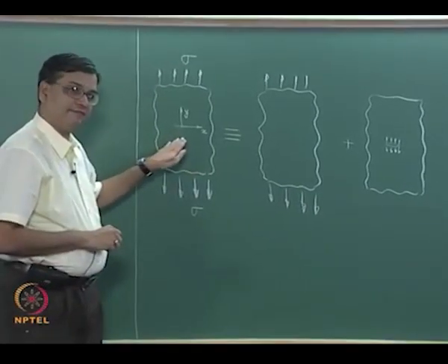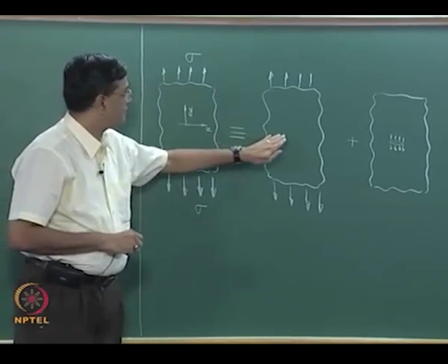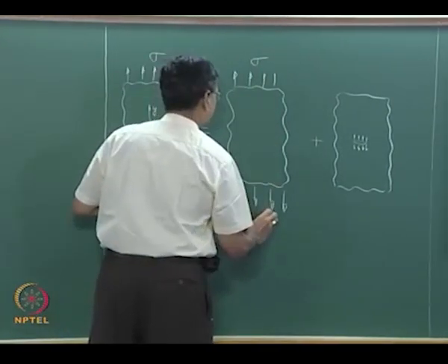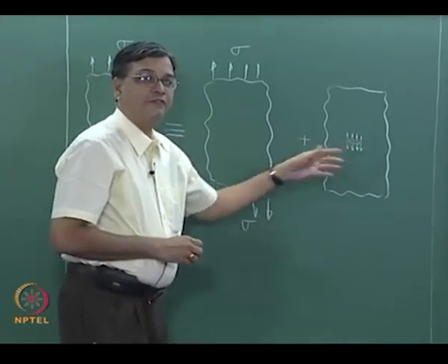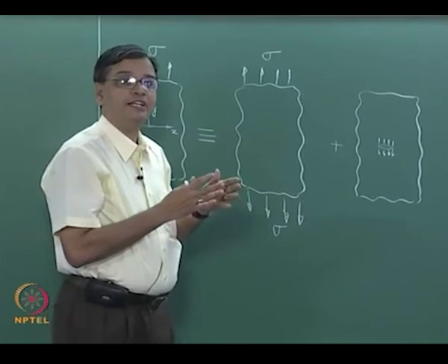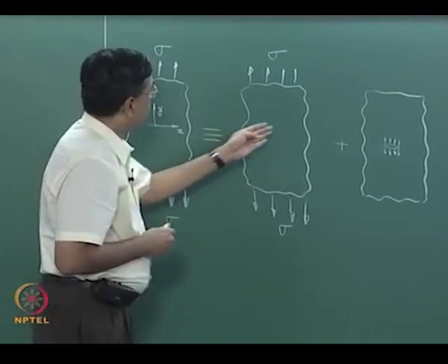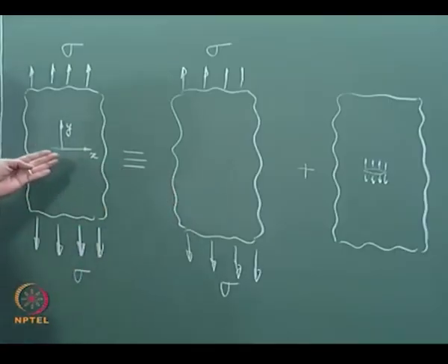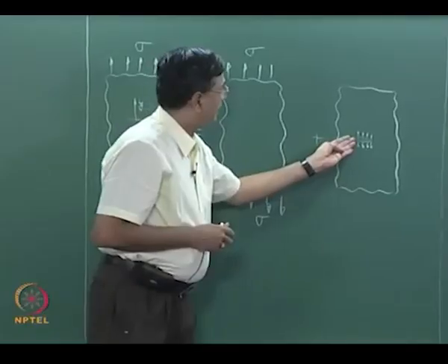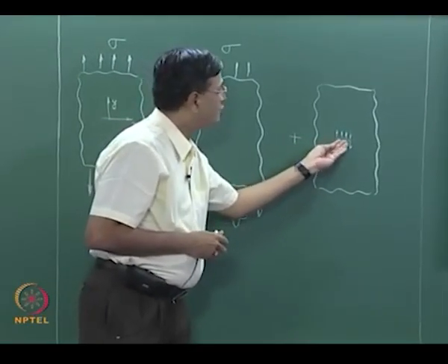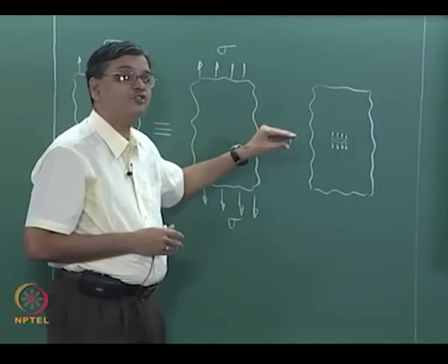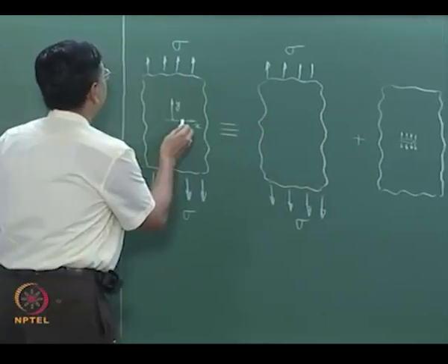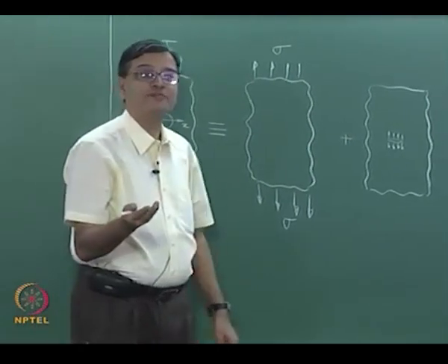This is the problem that I have. This could be thought of as solution of this problem plus solution of a problem like this. And from our knowledge of developing stress intensity factor, whatever the stress intensity factor I get out of this problem should be same as what I get in this problem. Here I have a crack and I need to know what should be the load, that is also needed. The crack needs to get opened up, and it should be opened up to the extent that what we have already got as your crack opening displacement.